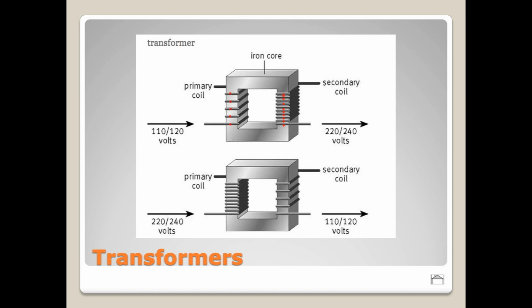What that means is when we run voltage through our primary coil, which has the 5 coils, it's going to create a magnetic field of a certain strength because of the concentration of the magnetic field. Remember, that concentration happens with the coils of wire. On the second side, because we have more coils of wire over here, that magnetic field gets picked up in a stronger concentration. And so we actually get more voltage out.